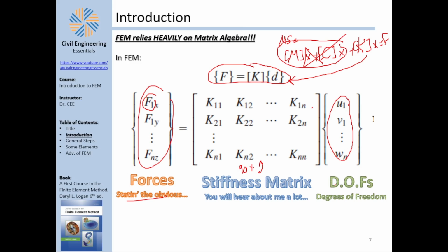We're going to talk later about what degrees of freedom mean, but basically those are possible movements of a point, because some movements are restricted. Allow me to explain very quickly. If you have a cantilever beam like this in a two-dimensional setting, what are the possible movements of a point in a structure? It could move in x, it could move in y, and it could rotate around the z-axis. In a 2D problem, those are three modes of movement.